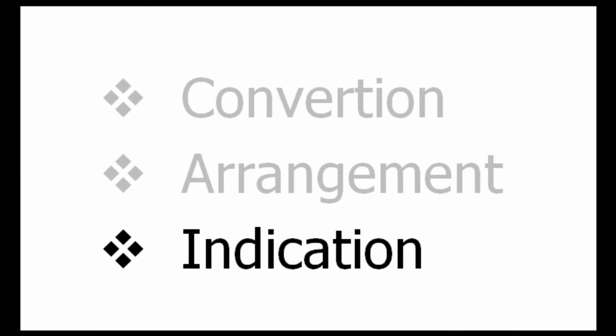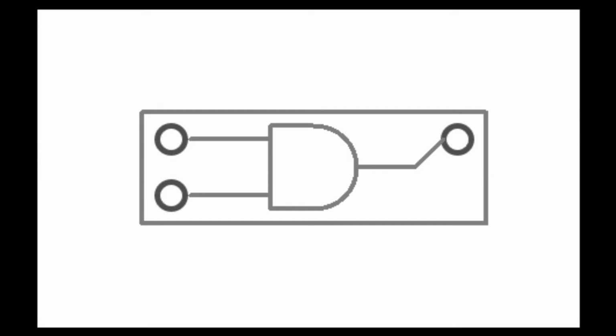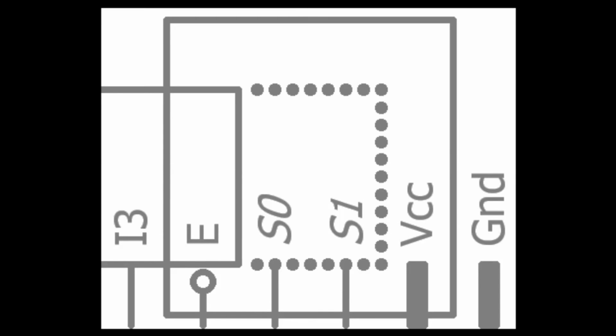Instructions and tooltips. Since the package is soldered on the bottom, there will be a significant area at the top for silk screen, which can be used for symbol-based tooltips. The IC is represented by a general logical symbol as much as possible. Inverted I/O and pins are represented by a small empty circle at the end of the pin. Package-related extra features are represented by a dotted rectangular area, like common clock, all enable, or chip reset.